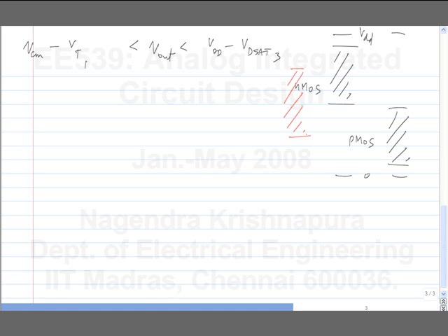Now what happens with body effects? Yeah, there will be some nonlinearity. The upper threshold will fall more. So the swing limit will reduce even more. So it may be something like this. This is at the source follower output, and this is with body effect.